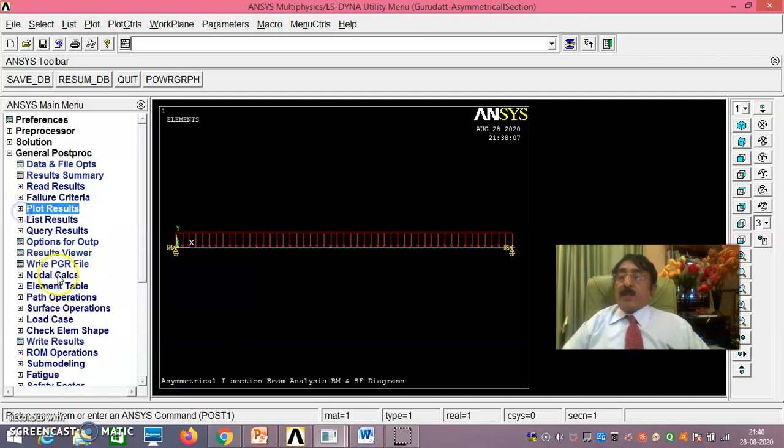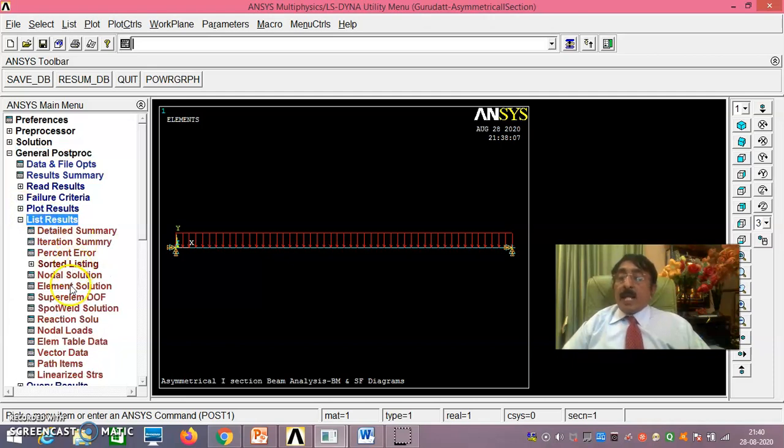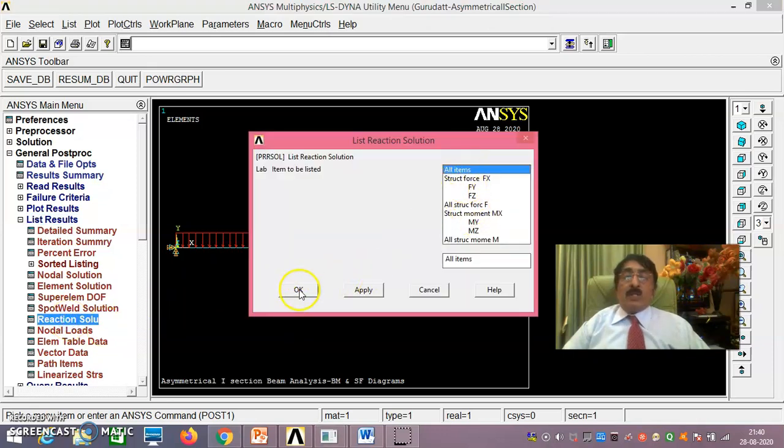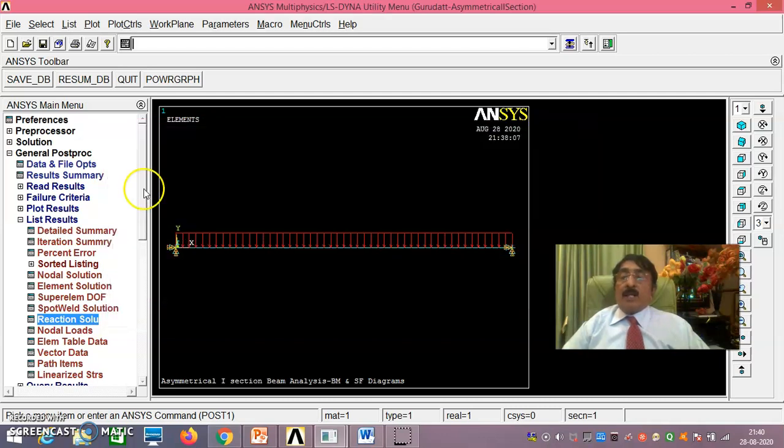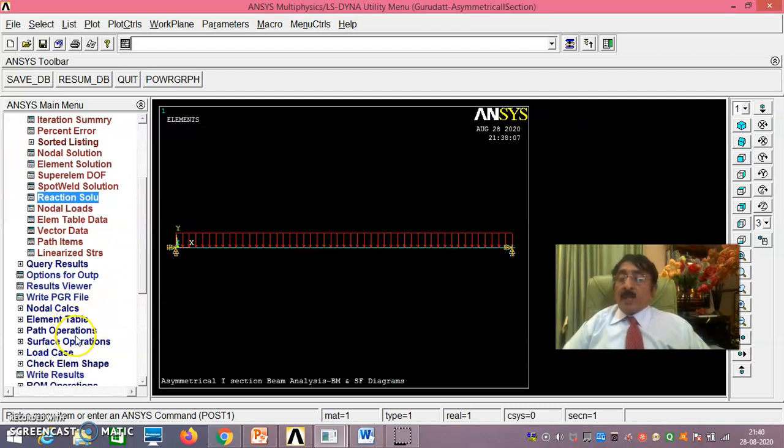List results, reaction solution you see. Reaction solution you should know it is 30,000, 30,000. You see 30,000, 30,000 at node 1 and node 2, that is first and last. That means you are done correctly. This we already proved by theoretical method, 30,000, 30,000. Now you go for element table.